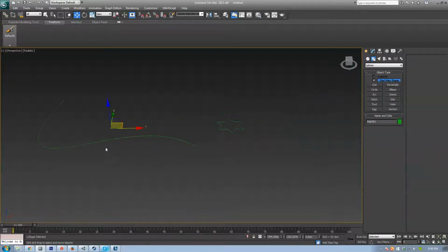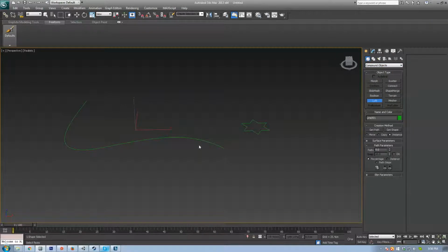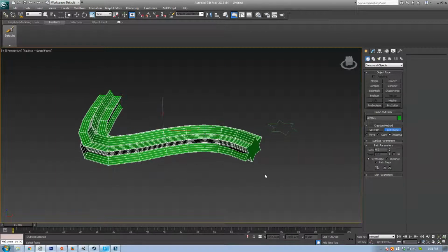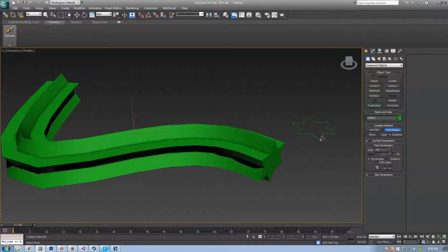It's in a bit of a strange place, but if you go into 3D Max, excuse me, you go under your geometry. Instead of going under standard primitives, go under compound objects. There's a sweet little tool called Loft. And I have my line selected here. With Loft, you have 2 options in the beginning: get path or get shape. Since I already have my path, I'm going to click get shape, and I click my star. What it's done is it's taken my star and run it along the path of this spline, allowing me to have a 3D object in the shape of this spline.